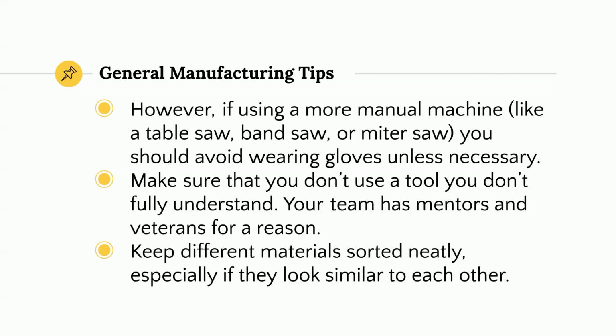However, if you are using a more manual machine like a table saw, bandsaw, or miter saw, I'd actually recommend not wearing gloves. Even if the metal shards can technically cut you, the gloves sometimes, some people have said this, make it slightly harder for you to know the location of your hand, and you might get your hand too close to the saw and whoops, no more hand anymore. At least you can probably get some disability pay in the future for it.